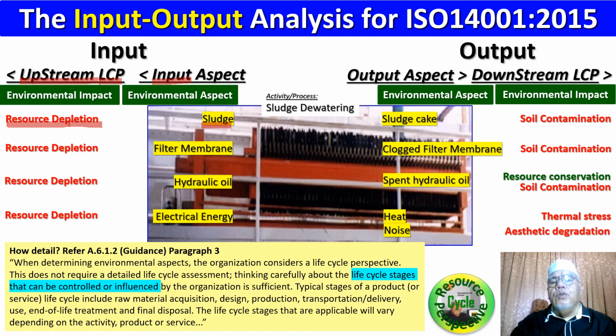And the output from this process is the sludge cake. This is a result of perhaps, in this case, coagulation and flocculation of the metal ions or other impurities, could be salt impurities, which are flocculated with the use of perhaps a coagulant aid or flocculant, which then settle down as sediments and it becomes sludge, and it is watery, so it is channeled to this particular filter press for it to press.